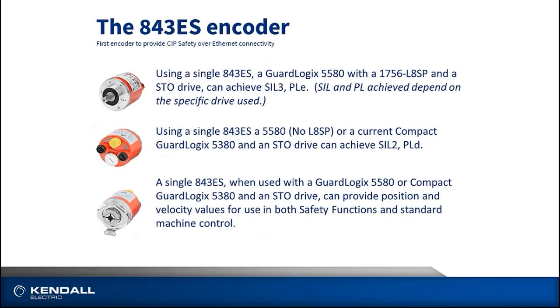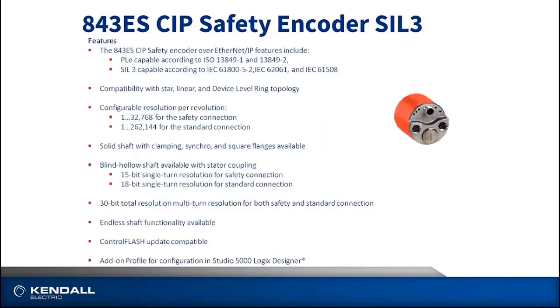With the GuardLogix 5580 and a safety processor, we can get up to SIL3 dual channel monitoring. With a 5580 without the safety partner, we get up to a SIL2 PLd rating, and we can provide position and velocity values to both the safety and the standard machine functionality. It meets ISO and IEC standards for safety.